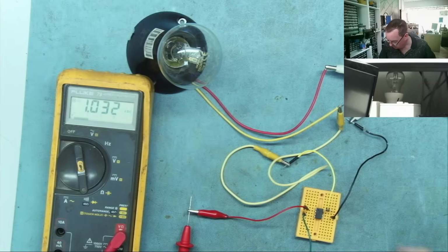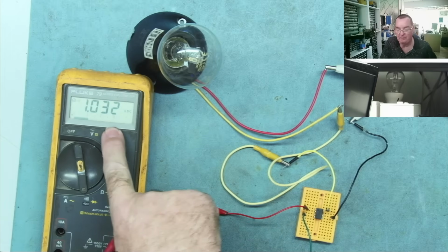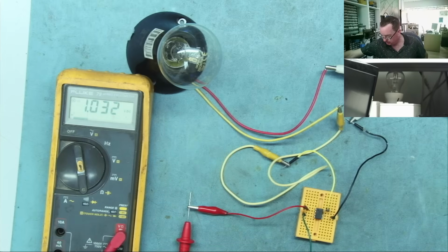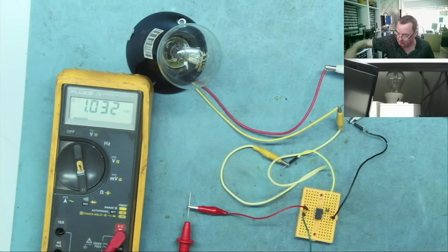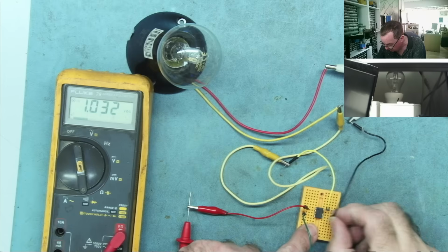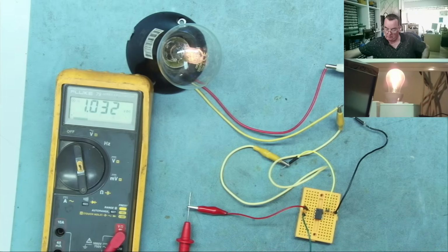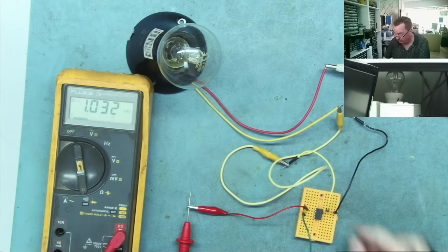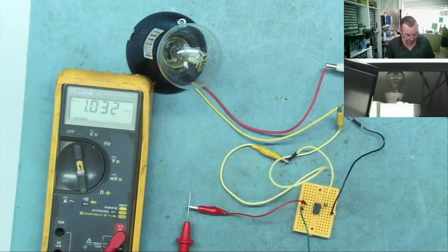Okay guys, so I've got it connected up. I have the multimeter on the LED. We can see the LED voltage drop there. Switch it on and nothing happens. I've actually got both light bulbs in series and that one's a lower wattage than this, so that's actually going to come on brighter than this one if it works. So let's just short these together. Both light up.